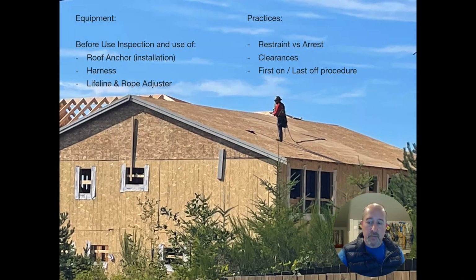As there are exceptions in most construction regulations for people to get onto the roof of a house to install the anchor without any fall protection, providing that is done before any of the work begins, and then the same principle is getting off. So it's the first person on, last person off principle. So this is another example of how the hazard assessment, looking at the equipment and what are the practices expected of that person, populates the content of your training event.